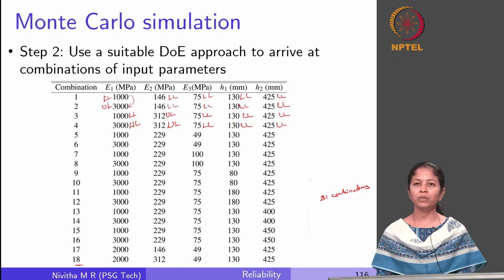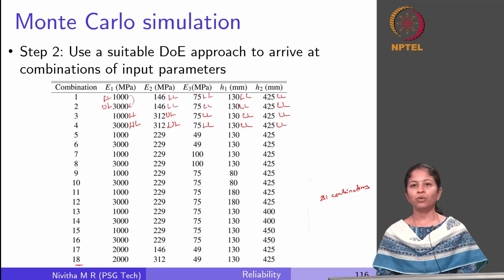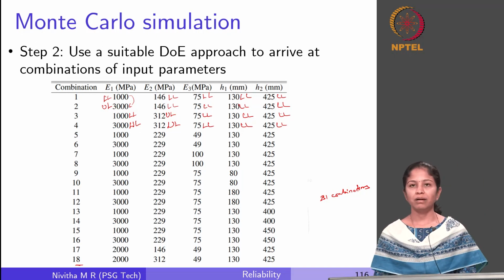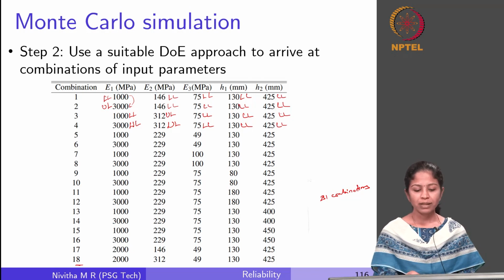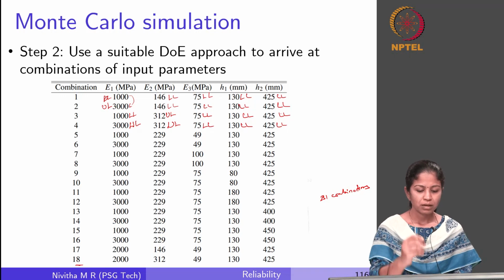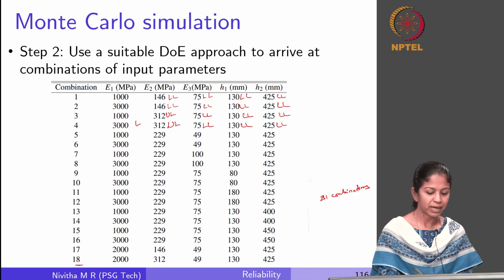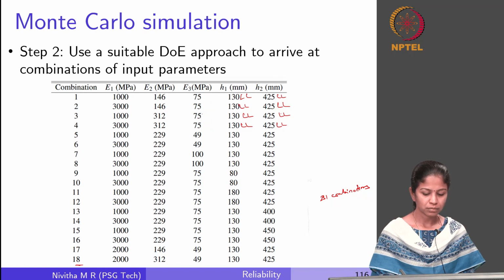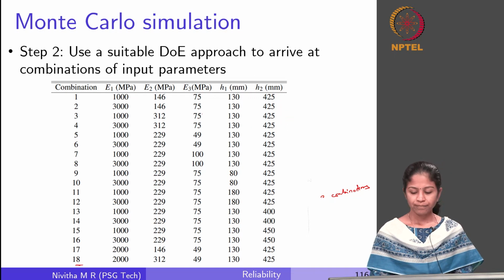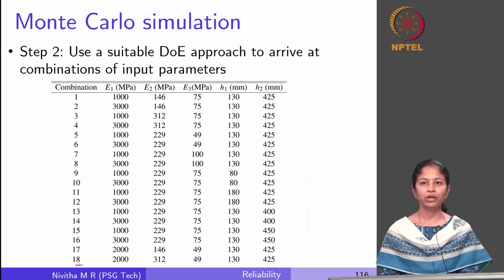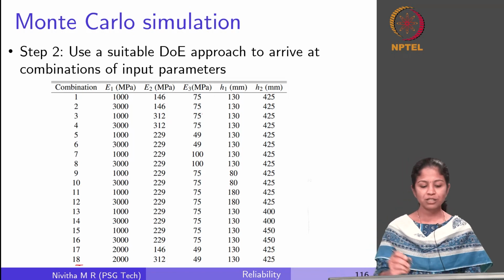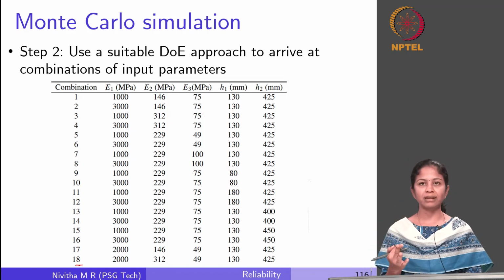So now what am I going to do with this experimental combination? So we know how to do a pavement design using IRC37, right, the IIT Pave software. So now for the first let me just erase all these things to explain it better. Right. So now let us take the first combination. I am going to take my IIT Pave software, right. I will be using only 3 layers.